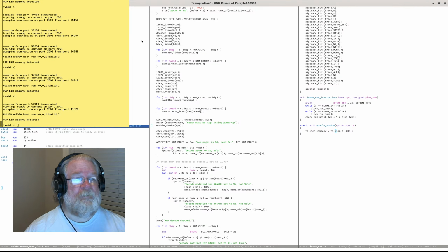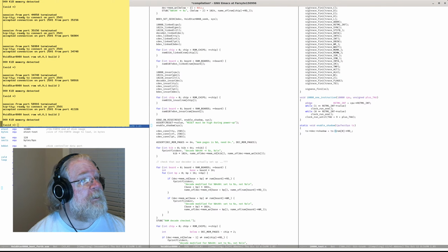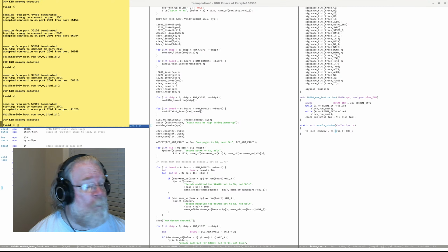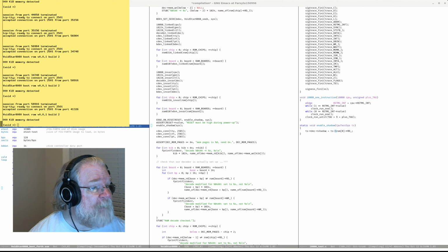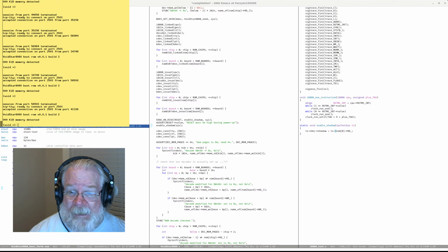So what I'm going to do is spend some time debugging this on my own and not on camera, to see if I can figure out why we are not able to read the memory. We should be able to write a value at 0 and read it back and get the data. We have tests that do this. Why is it not working this time?